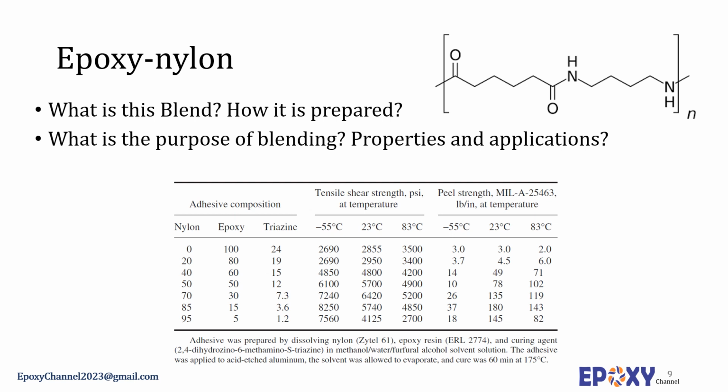These resins can be dissolved in alcohols and other solvents, and they can be melted below their decomposition temperature. A preferred solvent mixture is ethanol plus up to 20% water. Epoxy nylon resins are one of the best materials to use in film and tape adhesives for applications where the surface environment is not severe.